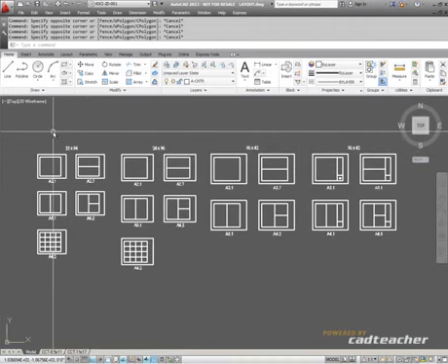So if you were to generate a set of construction documents at a 22 by 34 title block, you could print those drawings at half size and they would appropriately fit on an 11 by 17 sheet of paper. But again, these are the standard size title blocks with which we have to work: a 22 by 34, a 24 by 36, and a 30 by 42.